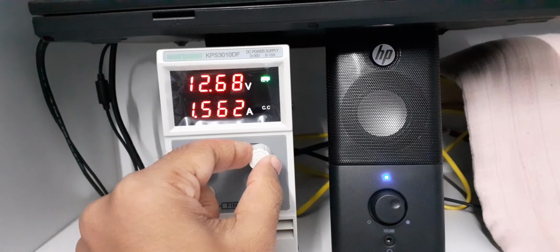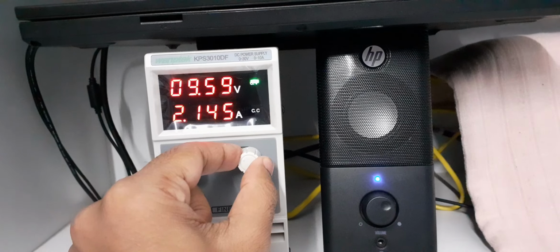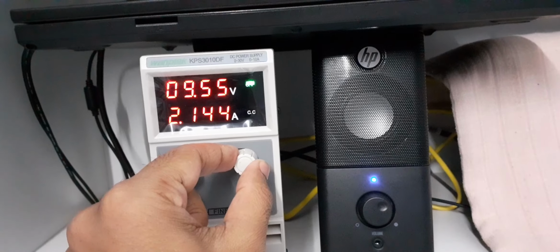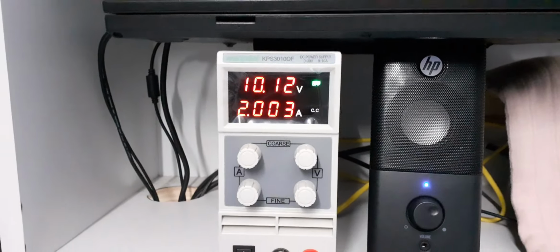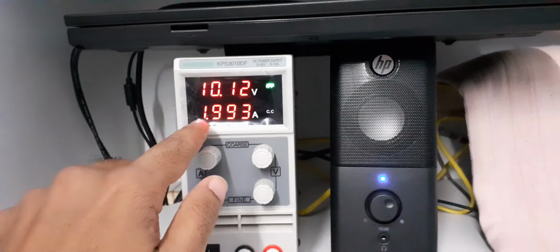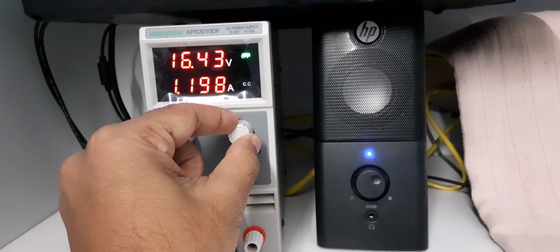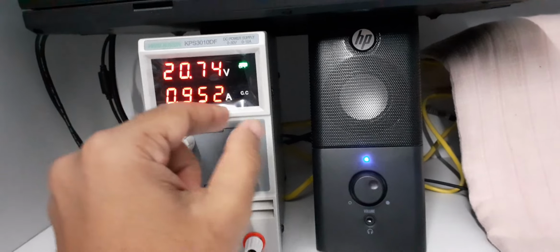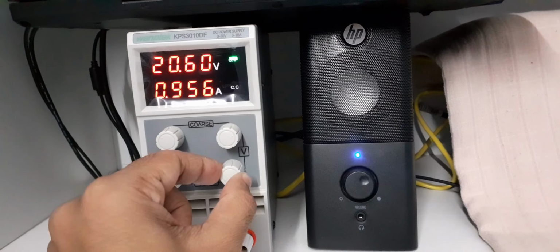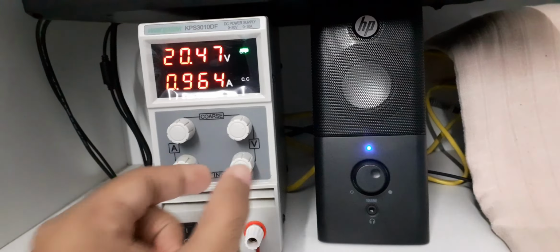To verify that, I will go to about 10 volts, and the current is 2 amps. So 2 amps at 10 volts is 20 watts, and 1 amp at 20 volts is again 20 watts. So the power remains constant at 20 watts, and this is again useful in testing certain kinds of